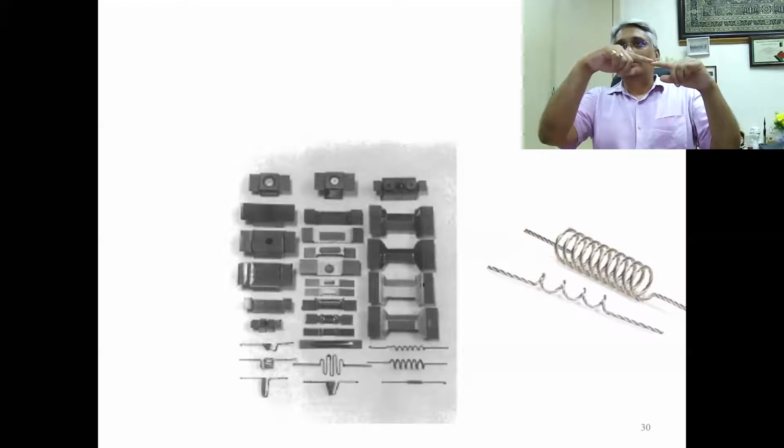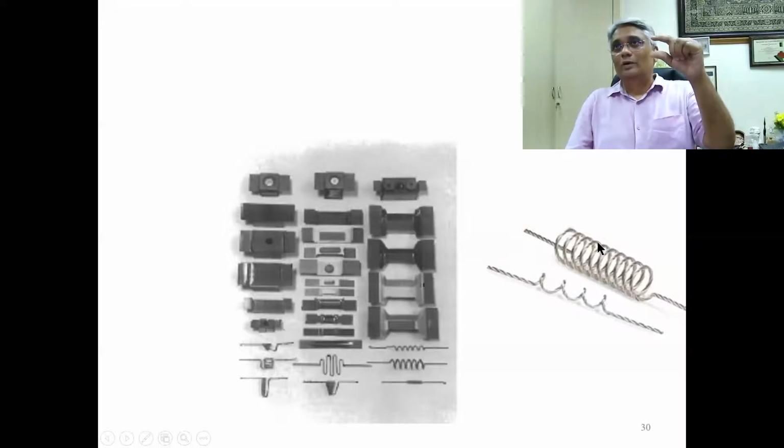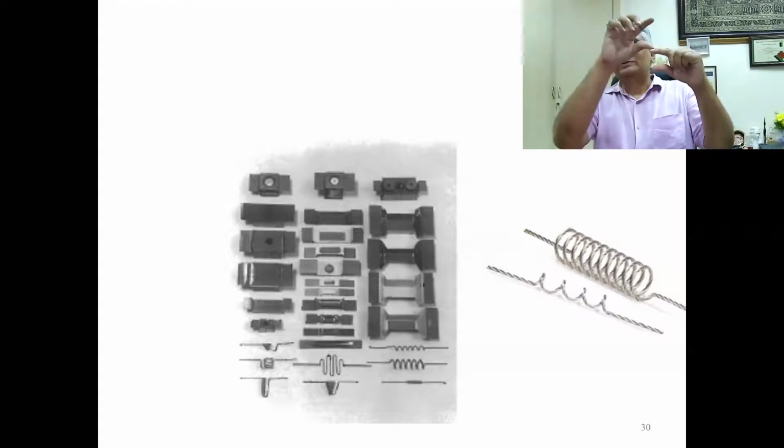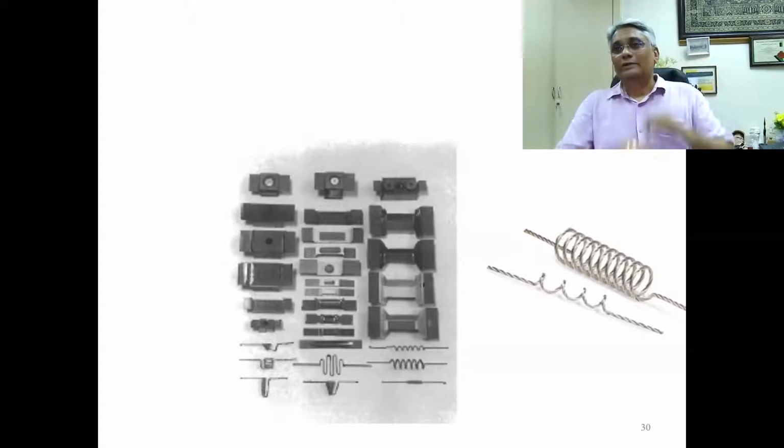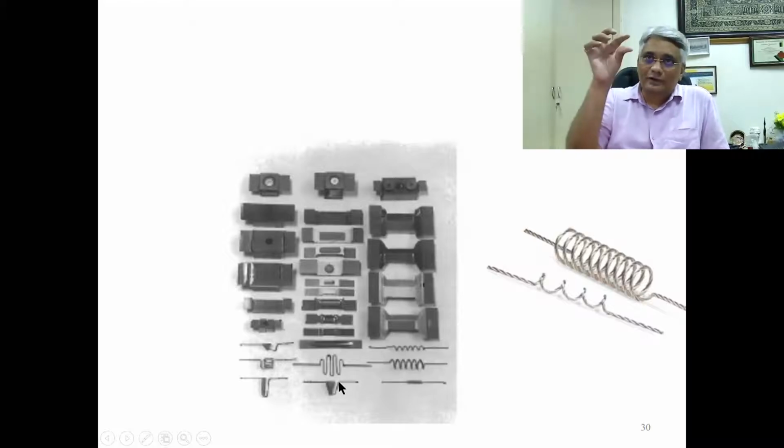Now the initial charge in the case of a wire wound in the form of a heater, which is 1 inch in length, the charge starts there and then it drops. That means you have changed the distance between the source and the substrate by 1 inch, which is not good. And in order to avoid that, to some extent, these conical baskets are used, with shortened length.